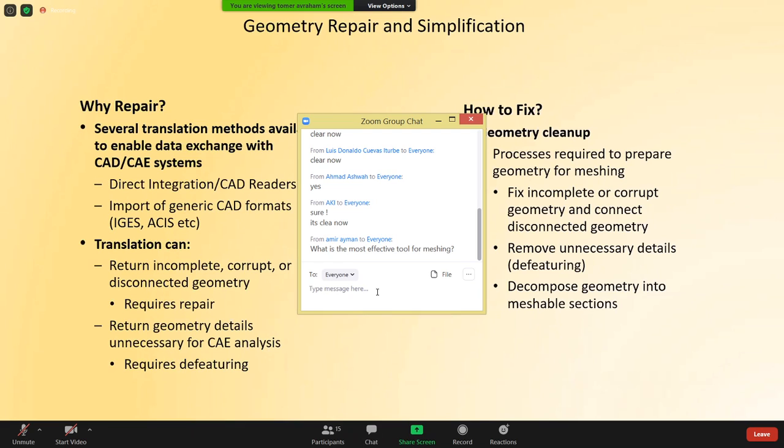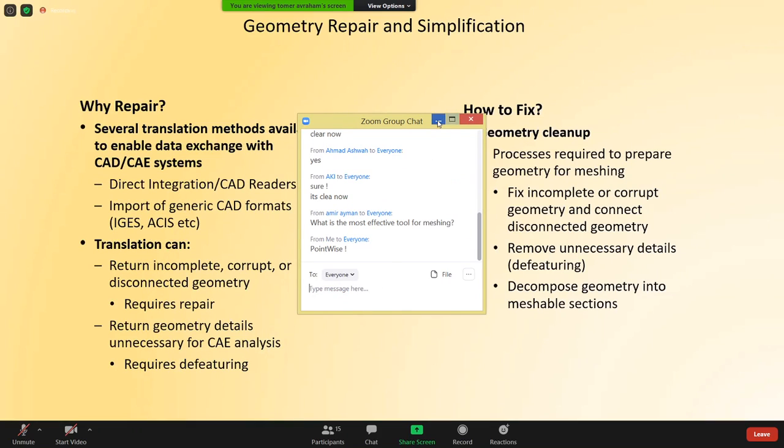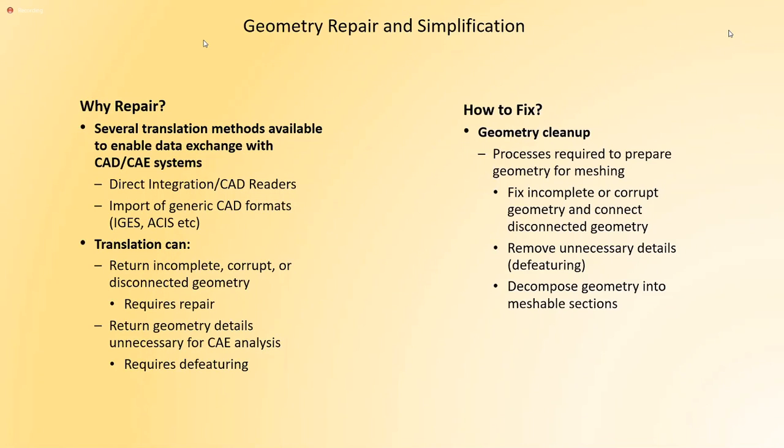Always ask the designer to give you an XT file. Okay, it's very important because the way he translates the problem might not be the way that your software translates the problem, and that could cause real issues.